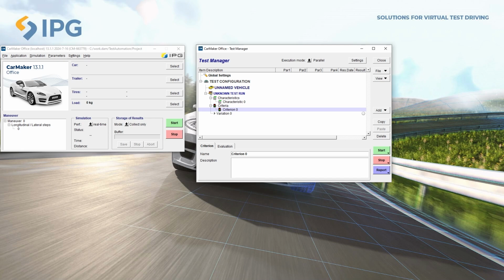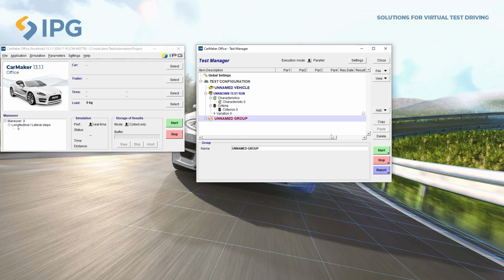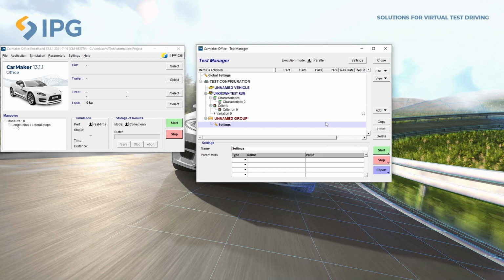Another additional setting is to group multiple test runs or multiple simulations together. We also have the possibility to add additional settings in which we can define pre-processing and post-processing Tcl commands via external Tcl files. They can also be set up from here as individual script control commands that can also be given by a Tcl file, if not needed otherwise.